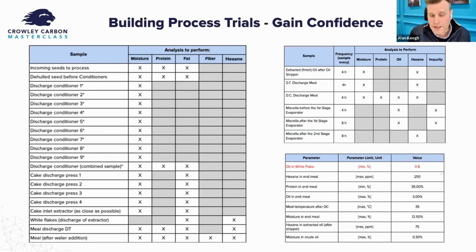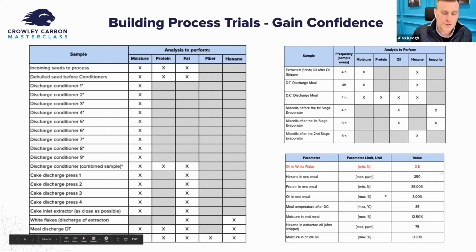And then in that case, to make the change, you can build process trials. So with quality, you can build process trials like, making sure you're doing the right analysis, the lab analysis, the quality analysis, that the frequency of doing that analysis is agreed and checked. You're doing it as frequently as you can. You're monitoring certain parameters to make sure that there's no knock-on effects downstream. So you're doing it in a structured, controlled fashion, using the mass and energy balance, using the data coming from the plants that you've already gathered, so you can see everything, and you can see everything downstream, and you can bring on board the quality people if required.